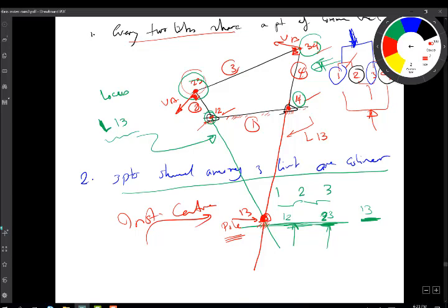Similar to 1,2 and 1,4, they are both instantaneous centers. The difference is that links 2 and 4 do only rotation, but link number 3 does general motion, so its pole changes position in the plane, as we discussed before. The path of point 1,3 on the plane is a fixed centrode, and if you draw the same path on the moving link 3, you get a moving centrode.